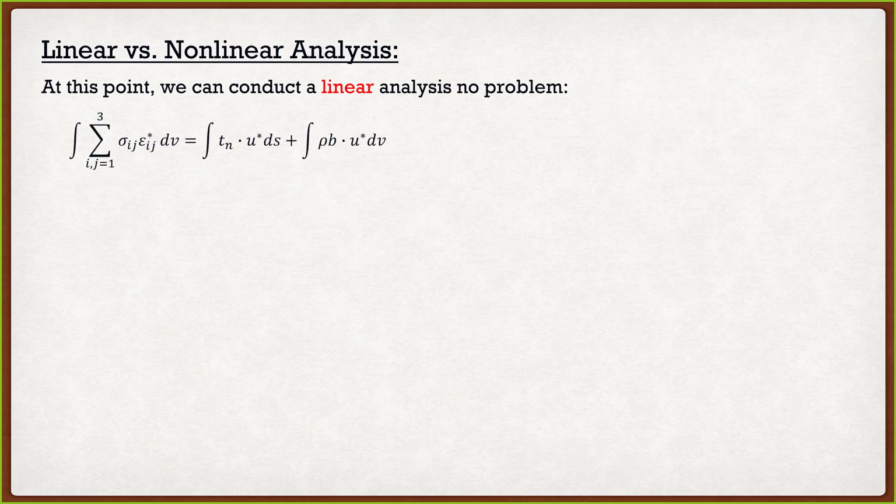Well, when we were deriving our equilibrium conditions for our solid element, we basically had this formula, and then we were able to use a bunch of linear elastic assumptions to create this formula that you guys now know and love. Now, we made further modifications to this formula in the fact that we dealt with those integrals. So instead of just B transpose C times B, we now have a determinant of J, and we know that we're integrating from -1 to 1 in both directions. So this is still the more general form, but you guys know where this equation basically comes from.